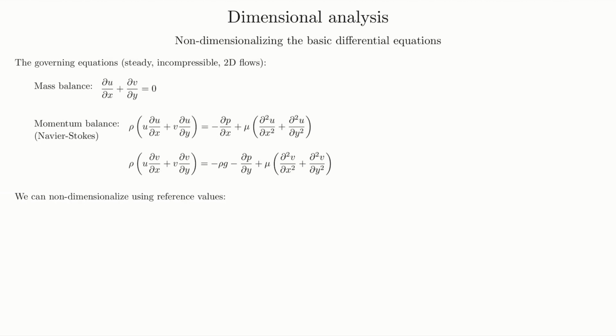Okay, now we start by non-dimensionalizing each variable, and we do that with reference values. Now, the basic idea here is that ideally each variable goes roughly from 0 to 1. We definitely want to try to keep all of these to order 1. So I'll write these out, and as I write x prime and y prime, the prime one is the dimensionless one. So we're writing L here, where capital L is our reference value. And basically any problem you're dealing with, L is going to be the dominant length scale.